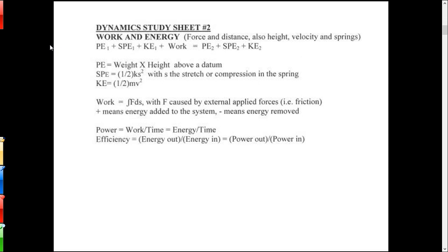So the potential energy is the weight times the height. You call out your own datum wherever you want it to be. It's fine, but once you establish it, stick with it throughout the whole problem. You can't be moving it around in the middle of a problem.